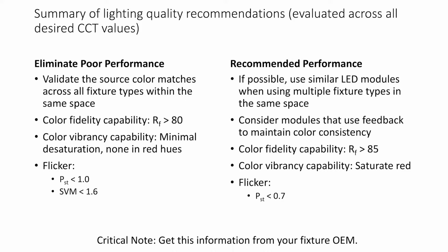Color vibrancy. Does my fixture desaturate in some colors? What about the red? We really like red, but for some reason in the old CRI measurement, we didn't even include red in the color palette that we typically represent. We only do the first 8 colors, and the 9th one happens to be red, because LED was pretty poor at red for a long time. It's now quite good at it.